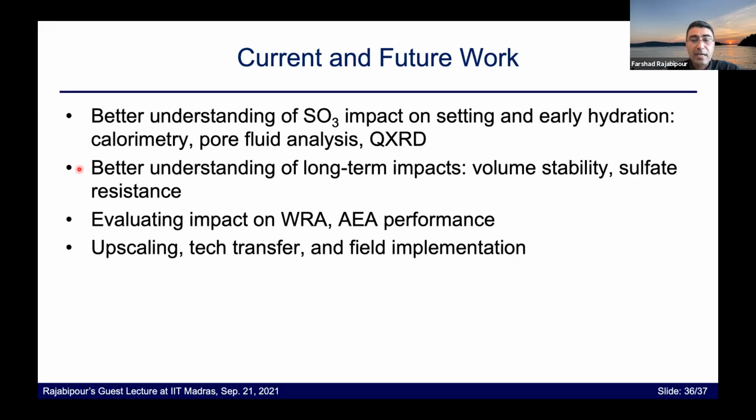We're also looking at longer term impacts in terms of volume stability, sulfate resistance, and again, how these can be mitigated. We also are going to look at how the SO3 content would impact performance of water reducers and air entrainers. And finally, looking at upscaling this technology to concretes, to field implementation and technology transfer.